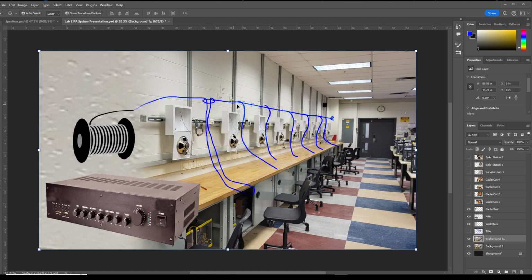Now, once you do that for every single speaker station, or whatever speaker station you're going to work on, tie it off here. You can tie it to this Unistrut rail here if you want. Then we're going to cut this loop here. Now, don't short yourself with the wire. Do not do just 8 inches or 12 inches. Run a good length so it goes right down to the countertop and maybe a foot over. Please do that, okay? Do not try to save 5 or 6 or 7 inches of wire.